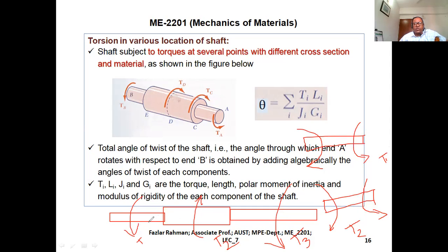So actually what I need to do is figure out the resultant theta of this whole shaft. Due to the torque, this will be denoted theta1, this angular deformation will be theta2, this will be theta3, if you make the free body. Then the resultant theta will be theta1 plus theta2 plus theta3. Some might be clockwise, others anti-clockwise. If you take anti-clockwise as positive, then clockwise will be negative. So you have to take the algebraic summation.